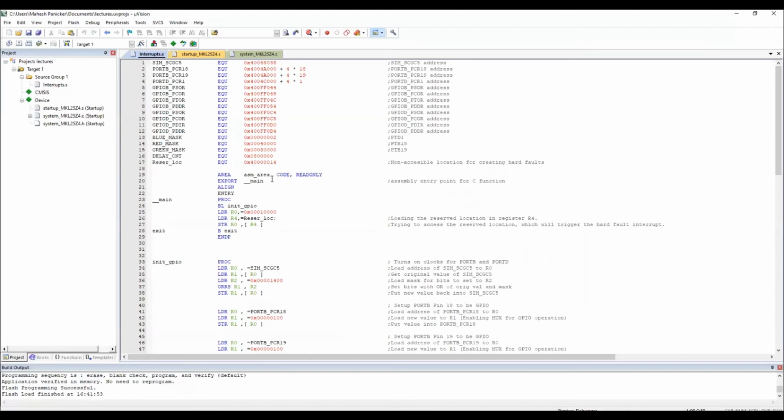A lot of things we can do with a single line of command instead of so many lines of command. Before introducing C, there are different ways. One is to directly use something like Keil or a GCC environment. The other way is an open source online cloud-based compiler, which I have a separate session on, known as mbed. So we'll go to that.